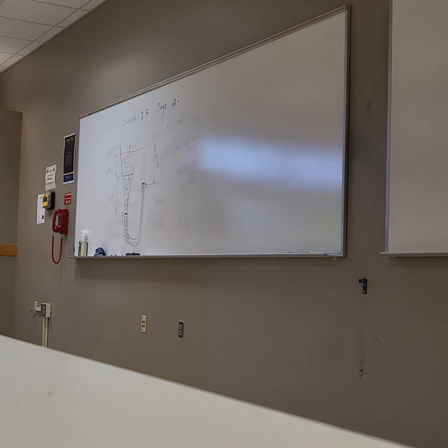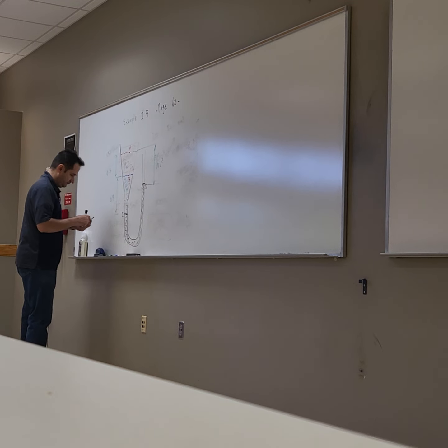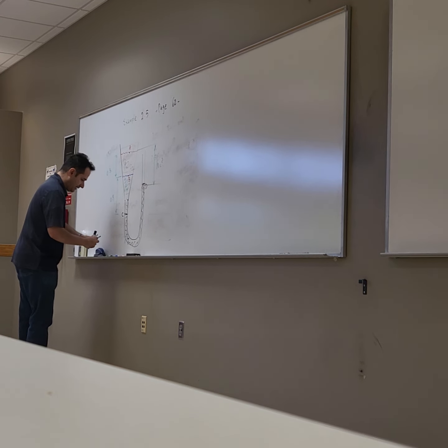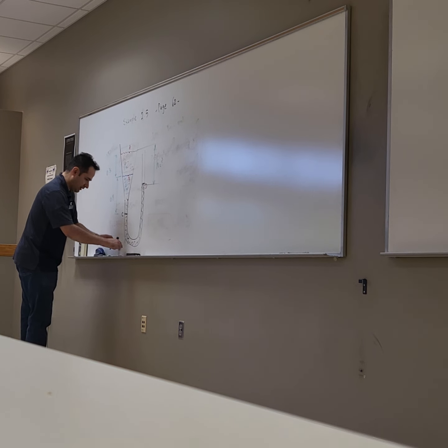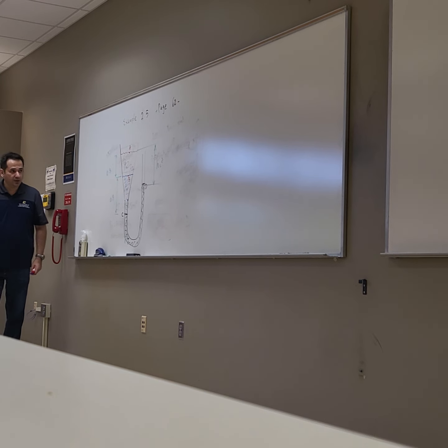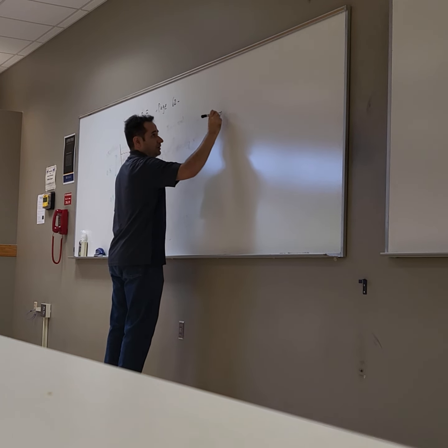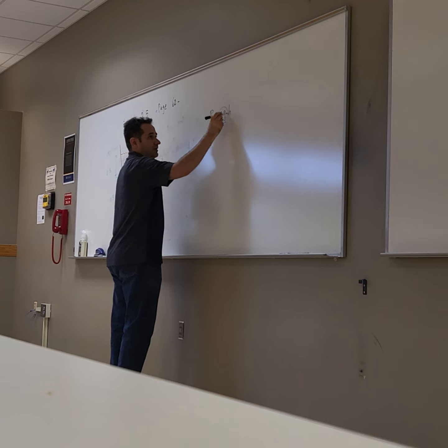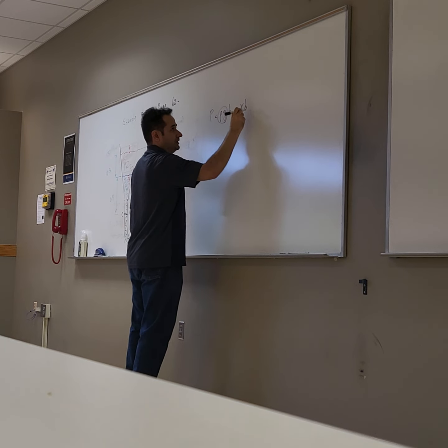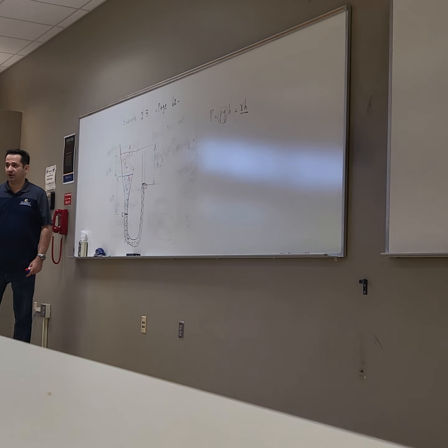So what should I do? You compute that height, H. Well, you can use the relation we developed, P is equal to rho g H, or simply you can call this gamma H. And you can write this between any two points, right?